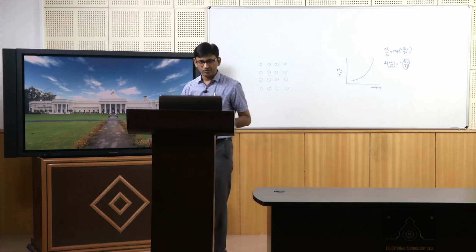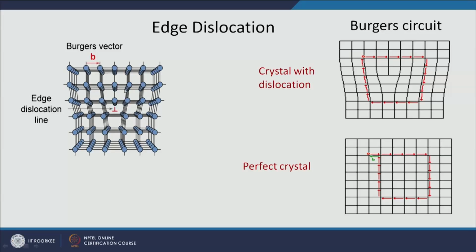Wherever the dislocation is ending, you can see that there is large strain in the atoms; the bond lengths in between are all stretched. So, you are inserting this extra half plane here.